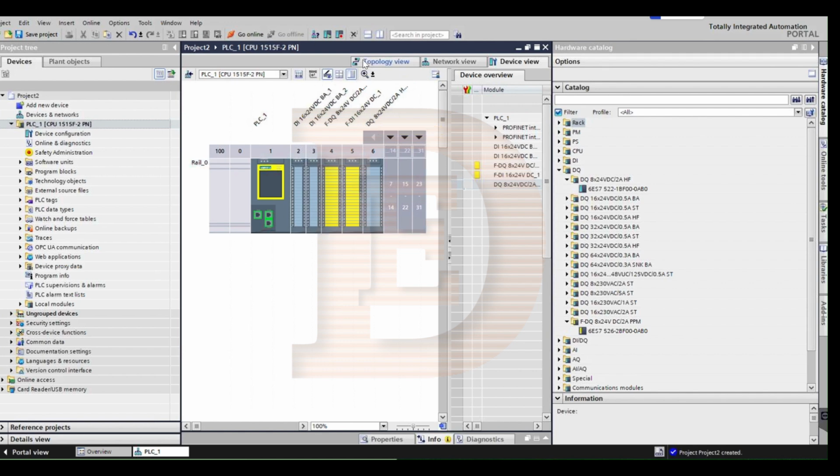The reason we do this is because the standard inputs, we never want to lose those. So we're not going to turn these off in any safety situation. Safety outputs are controlled by the safety program only, so we're not going to turn them off. These turn on the machine.